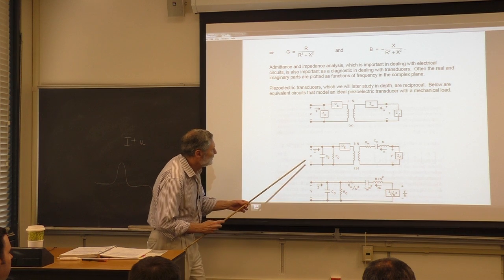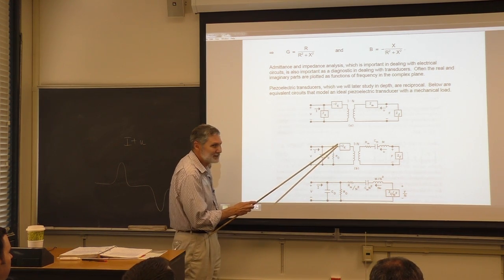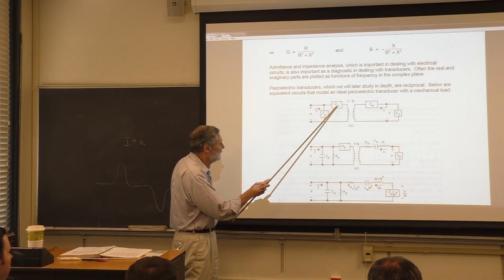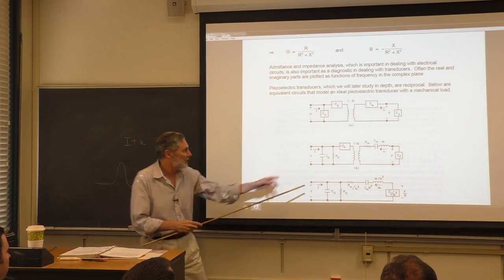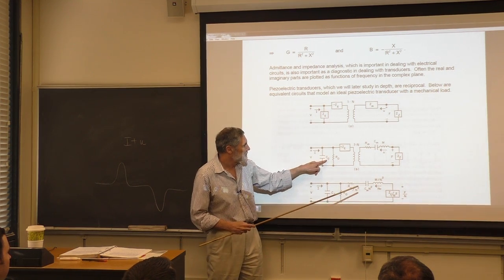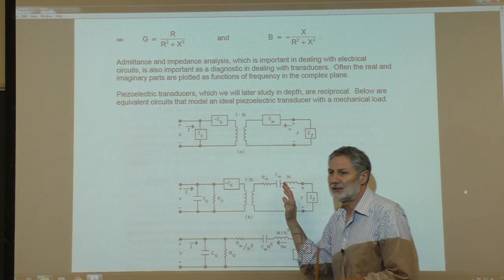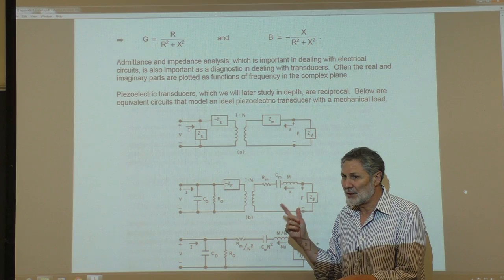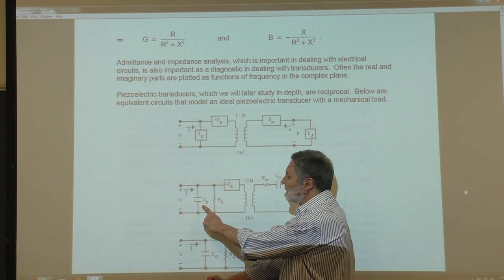Now, the left side is a little bit more complicated. Brian has left this here, and he doesn't explain this, okay? But I'll tell you what I infer about this. We've now specified what this is. This is a capacitor. Okay, so this C naught here is the capacitance when there's nothing coming from the mechanical side. It's called the blocked capacitance. What does blocked mean? No mechanical motion, U is equal to 0. So everyone calls this the blocked capacitance.